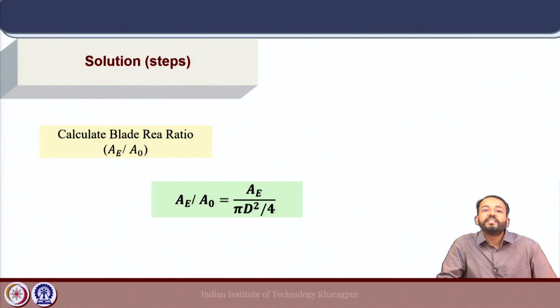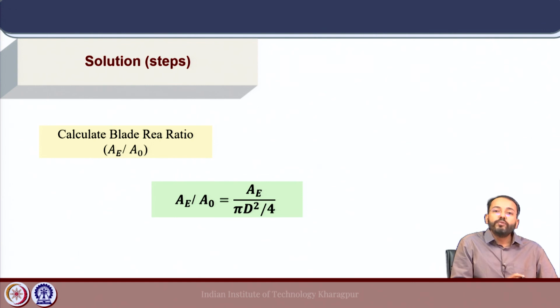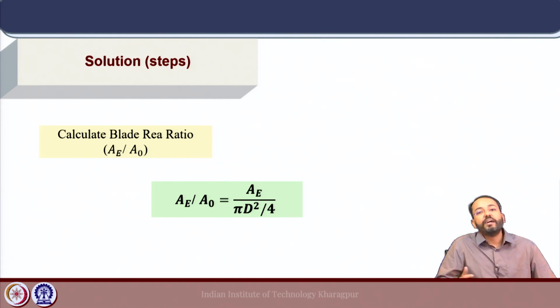Okay. So, the same problem can be framed in a different way. The idea is to calculate the parameters of a propeller based on cavitation criteria. So, this Burrill's cavitation criteria is used in propeller design as a cavitation check for certain operation conditions, so that the propeller blade cavitation occurrence is minimized and the propeller blade performance is not affected by cavitation.